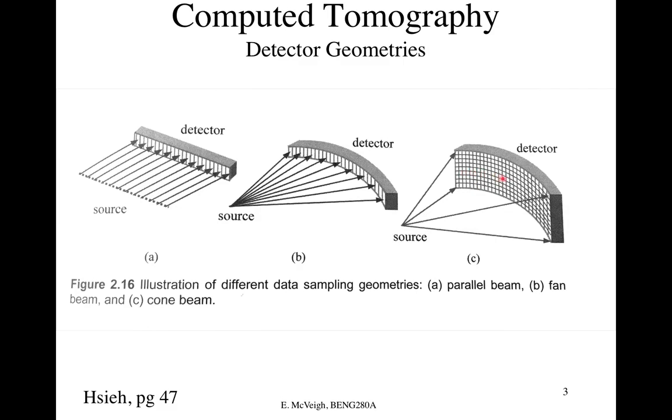Our sampling rate is fixed by this separation, but we can average these neighboring pixels, or dexels, together, and that will bring down the sampling rate. So you can just combine every two, and all of a sudden your sampling rate's cut in half, right? And the estimate of the number of X-rays you're getting is improved when you combine two together because you're averaging, right? But you get a blurrier picture. So that's true. You can drop the sampling rate.